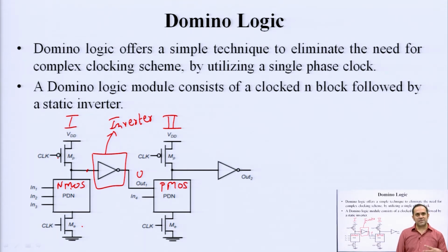So, now basically when you have 0 at the input, before the evaluation starts, there is no charge to be lost. Okay. The problem of cascading was that charge was getting lost. Logic 1 was discharging towards logic 0, but now you have eliminated that, you do not have any charge to lose here. Okay. So, if you have 0 by default, you can either charge to 1, which is a transition based on the logic which you are testing, or you keep a 0. There is no possibility of losing a charge, because you actually do not have any charge present to start with. Okay.